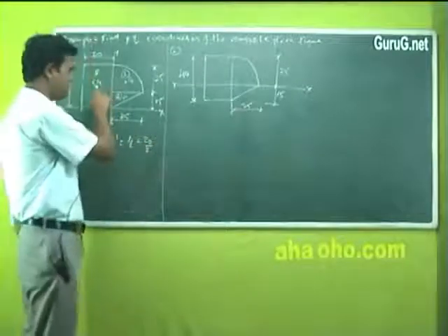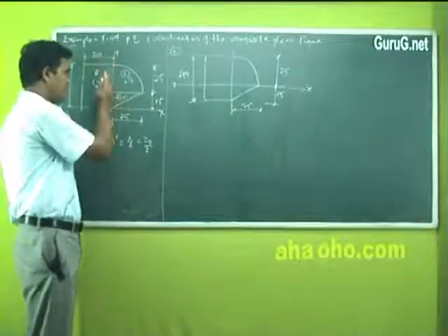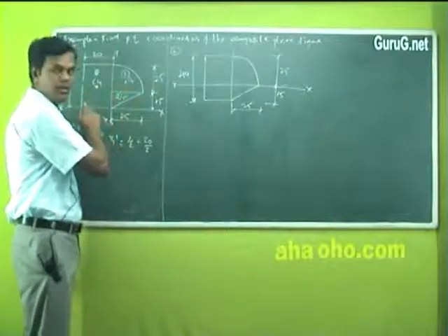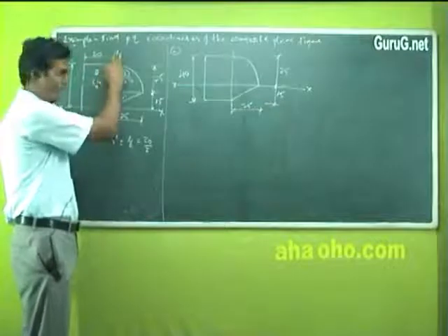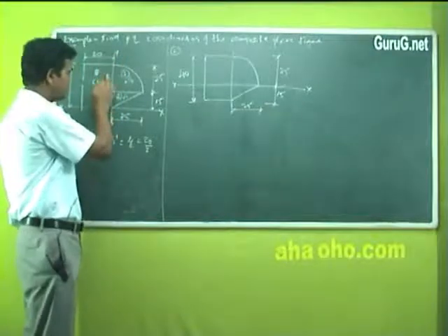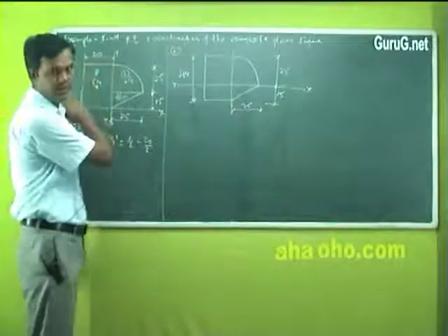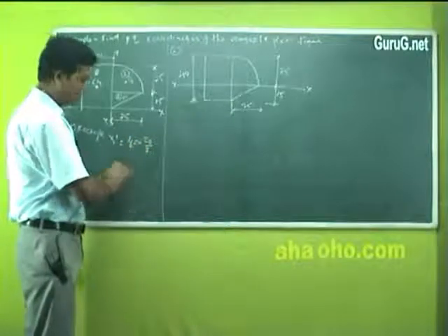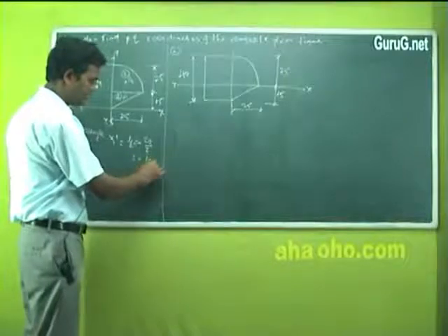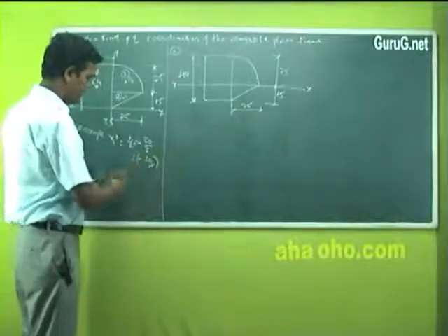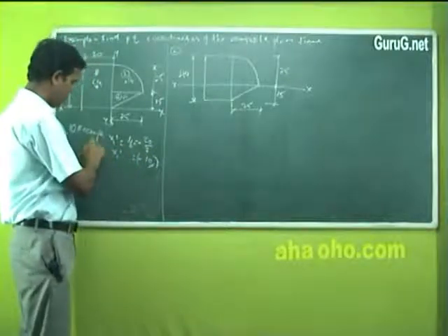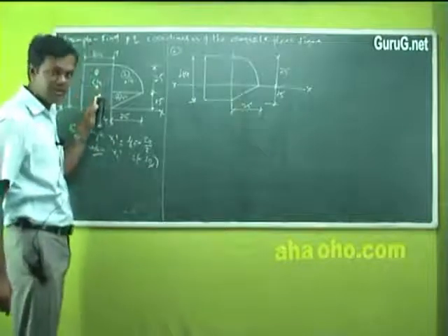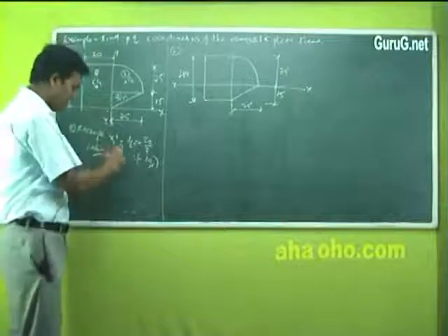I am finding out the CG, center of gravity, in x direction from the reference axis, which is y here. I am traveling towards x, meaning either towards right or left. This is x direction. So in the x direction from the y reference axis, the x values are on the left side of y. What is the meaning? It should come negative. Value is 20, but that is minus 10 meters. Is this clear? This is my x1 dash coordinate for this first figure, question number 1. Same figure, y1 dash value.